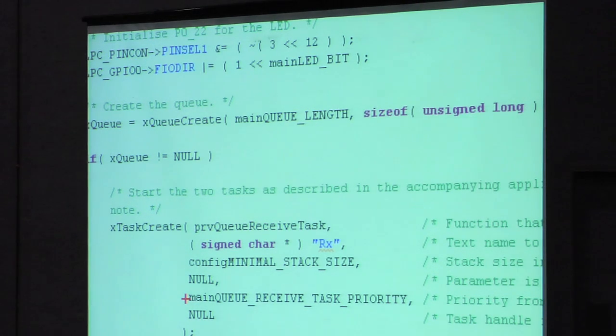The priority that we're assigning in FreeRTOS: the maximum number of priorities is configurable by a constant in FreeRTOSConfig.h, which we'll look at if we have time. If you set the maximum number of priorities to, for example, 10, then 0 is your lowest priority and 9 is your highest priority. The idle task is priority 0.